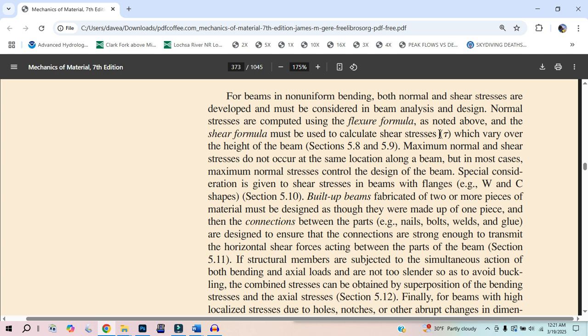So I can figure out the change in length on that outer tension surface and compare it to the length of the unstretched middle, and see if that ratio is going to be close to 0.002. And if it's over, you know what I mean?